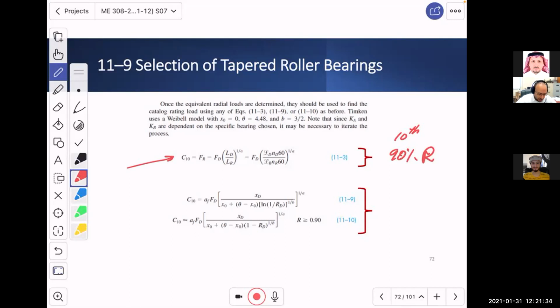If that's what you want, then maybe you have a different desired force than the rated force, or different speed, or different life. In that case, you use this equation where D stands for the desired entity variable, and R stands for the rated one.